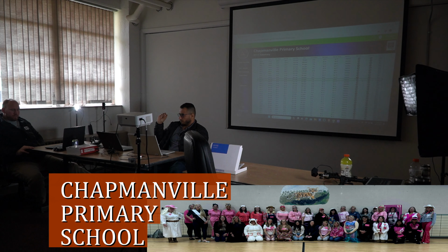Because if an alarm happened and somebody acknowledged it, you will see that the alarm had happened like 2 days ago and somebody acknowledged that alarm. So you'll have this log always there. And you don't need to worry about how long the list is, because the active alarms will always be on top. The acknowledged and reset ones will also always be at the bottom. So your priority of the active alarms will always be first.